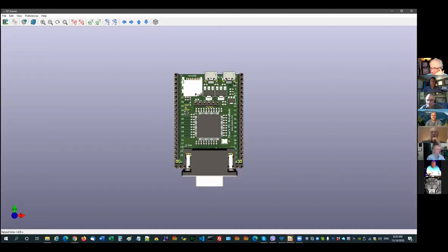There's two USB ports brought out. You might use one of them to supply the 5 volts because it requires 5 volts regulated. So you can get your 5 volts in by either of these two, or using the pins on the side. So there's a 5 volt and ground on the side. So these top 4 pins are 5 volt, ground, 5 volts, 3.3 volts, and ground. 3.3 is an output. So you could use the top 2 and provide 5 volts on either side, or you can provide 5 volts in this center section here.